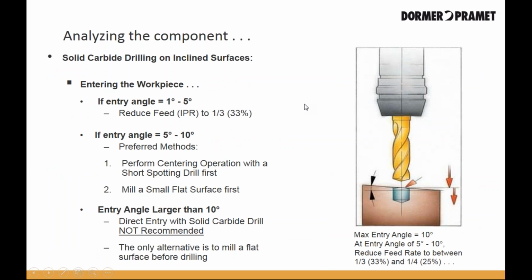In analyzing the component, you must consider the surface the drill will contact and how the drill enters the workpiece. One of the variables you will deal with from time to time is drilling on inclined surfaces. Using a solid carbide drill, there are some rules to follow to avoid drill breakage.